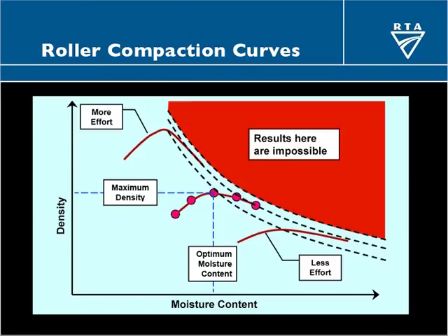So what you find is that you're filling the voids and overfilling the voids, but not getting the last bit of air out, and as a result the density is going down rather than up. Now that may be manifested in the field in various sorts of instability. The fill may start moving around, or you may get local shearing in it, but you won't really get beyond that point.